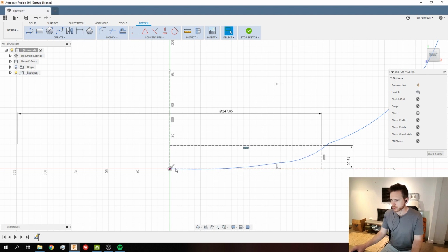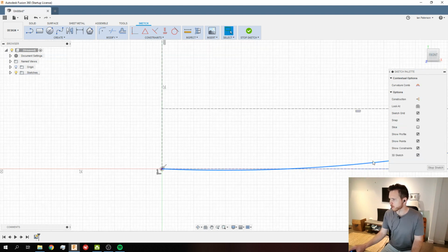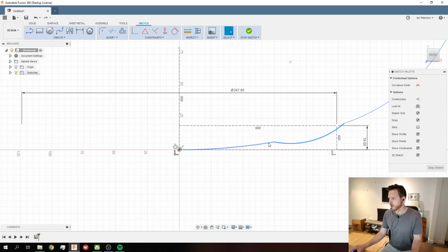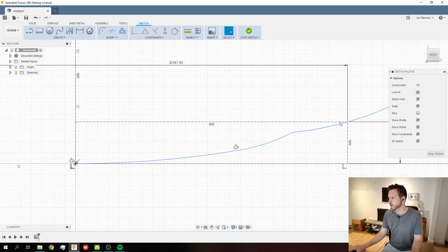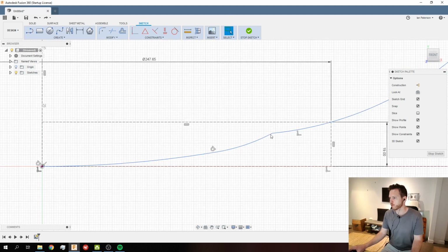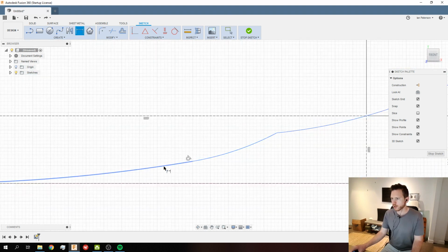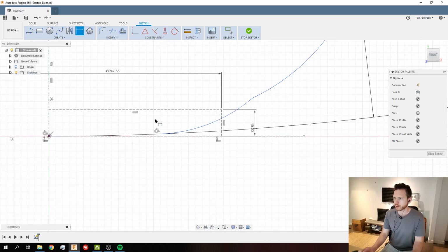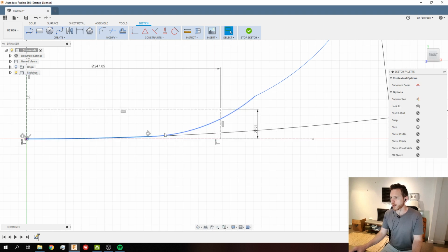It's resurrectable. So I'm going to make this line tangent to this line, because you don't want some weird feature in the center of your deck. So now that's up here. We need a bunch of tangent constraints on these, but I'll leave this one unconstrained for now, because sometimes, if you're dragging around elements, they can just get all messed up and weird, so no deal. I'm going to make this diameter something really stupidly big to start with, so it's essentially flat, and then I'll make this guy something manageable.